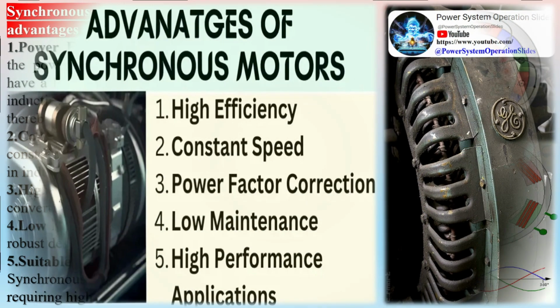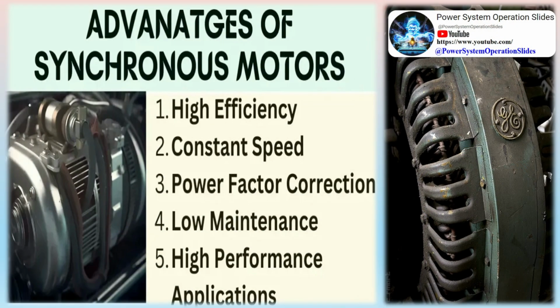An overexcited synchronous motor can have a leading power factor and can operate in parallel with induction motors and other lagging power factor loads, thereby improving the system power factor. Constant speed. The speed of synchronous motors remains constant irrespective of the loads. This characteristic is useful in industrial drives where constant speed is required.